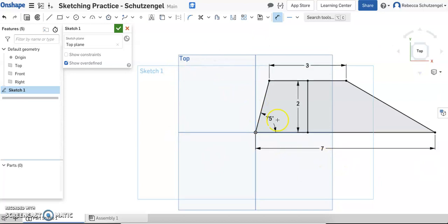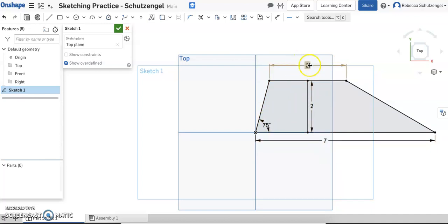Right, so I'm going to escape the dimension tool. So again, I'm still setting dimensions right now, but if I want to escape that, just press the escape key on my keyboard. If I want to move where I see any of these numbers, I can just click on them and drag them. That doesn't actually change anything about the sketch. It just can make it easier or harder to look at depending on where you put the numbers.